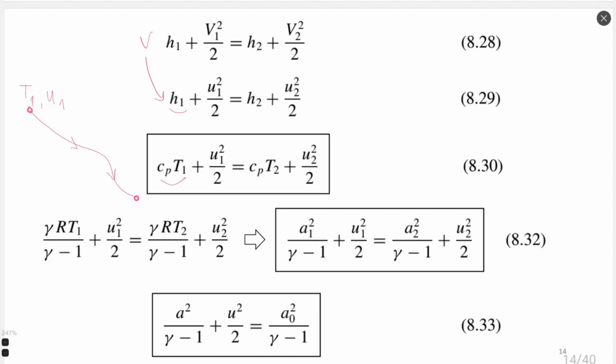And sometimes some equipment can just be difficult to install in one position or another. For example, a sensor of velocity usually is more complex than just a sensor of temperature. Let's assume we can put a sensor of temperature at the specific point where we would like to study our flow. So here at this point 2, I will put just a thermocouple, so I can measure temperature inside point 2.